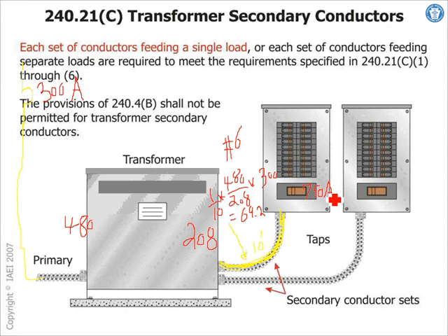The 10-foot rule for a transformer. I'm not saying that's how we size it. I'm saying that's the smallest wire that you can tap out of this transformer for 10 feet. Now, if your conductor can be 4 here, we're good. You see what I mean? But that's the smallest wire that you can tap out of this circuit breaker under these circumstances. Am I clear about the smallest, guys? Typically in a size like this the conductor would be 4, so we don't even worry about this.